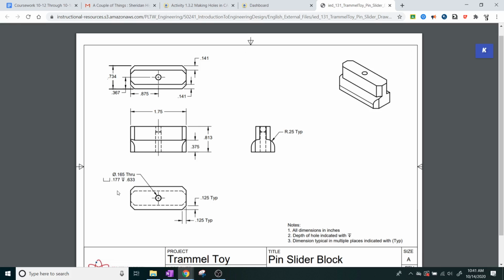We're talking like 1/100th of an inch bigger, so it's not going to be that large, but in the model, that's probably what we should do. Since we don't necessarily have a specific hole command in Onshape that I've taught you yet, we're going to probably just do two extrusions, a big extrusion for the hole and then a smaller extrusion for the hole. And then from there, we should be able to work our way from there.